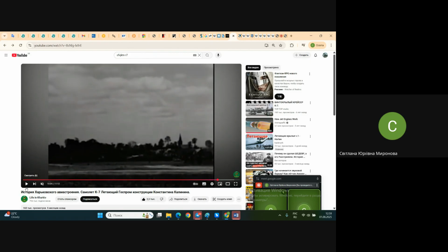The problem started from a sharp increase of the speed. After the sharp increase of the speed, it started trembling, buffeting of the stabilizer. This buffeting of the stabilizer resulted in the destruction of some structural elements, and the control surfaces practically did not exist at this moment. The airplane became uncontrollable and it stalled, as we have seen in this movie.